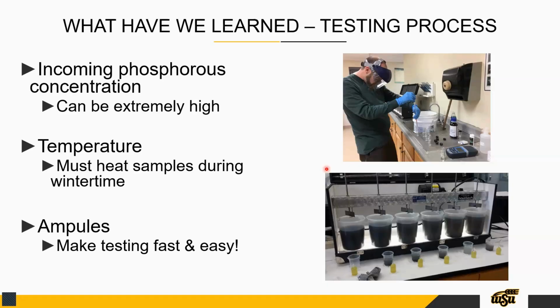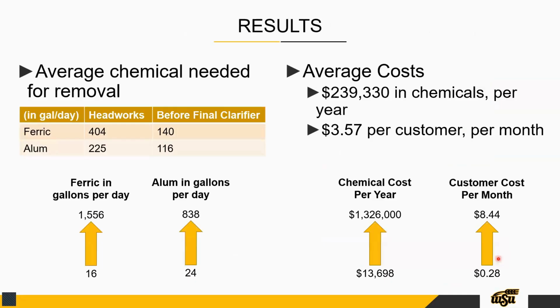That's going to make both chemical and biological phosphorus removal tricky. So additional process monitoring or maybe source control is useful there. And when you're running a lot of samples in a day, I actually don't think Hach makes these anymore, but there were ampules. They just fill up and then you run a test in them. You could be quite productive at that point.